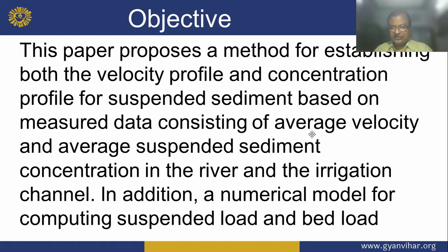The purpose is a method for establishing both the velocity profile and concentration profile for suspended sediment, based on measured data consisting of the average velocity and average suspended sediment concentration in the river and irrigation channel.